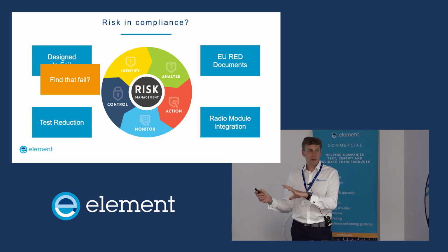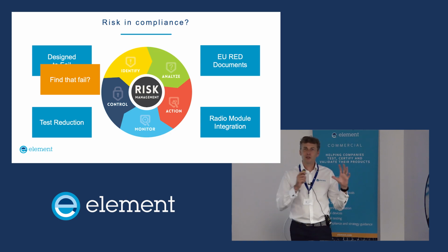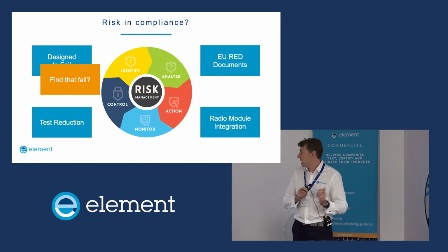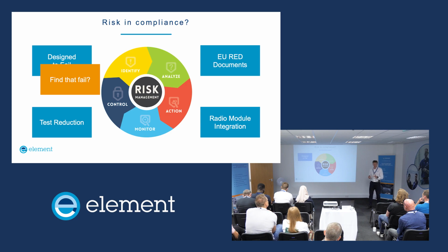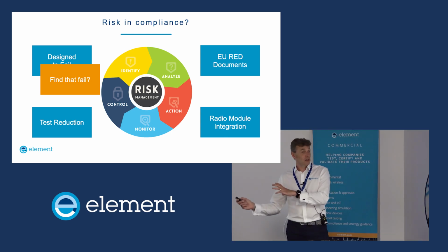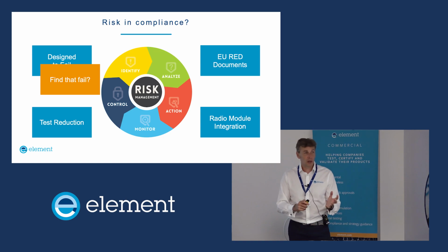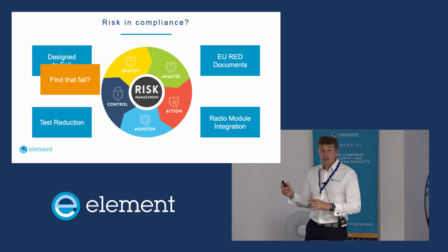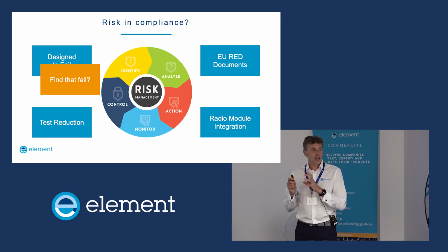So why would there be an approvals bit to go through if it's all about just passing a test? Well, here's a few things. Firstly, any failures from your product, when I say failures, I mean like it going into an unsafe mode, or it causing interference to something else, or something else nearby it causing your product to stop working, or any of those things, they're designed in.